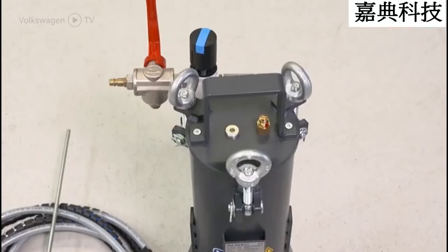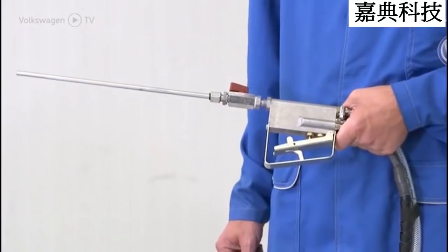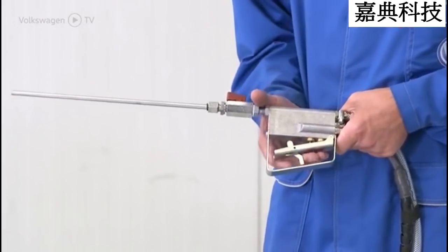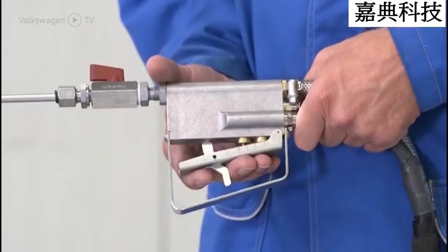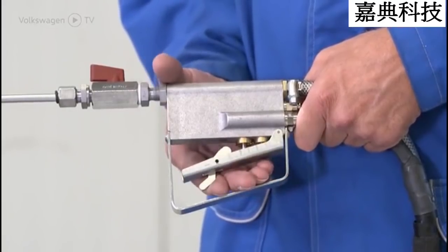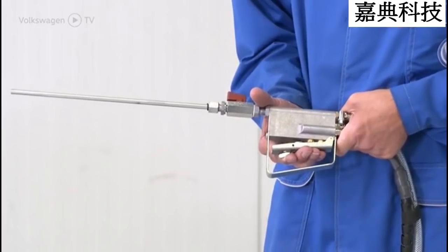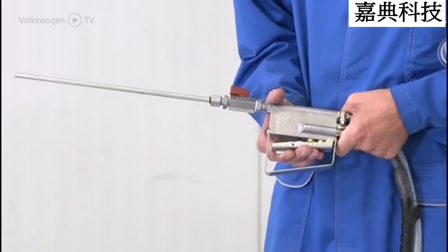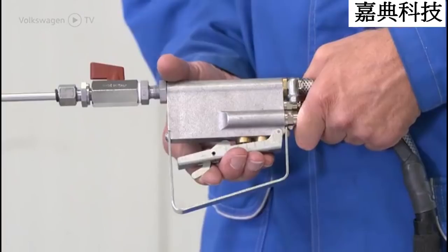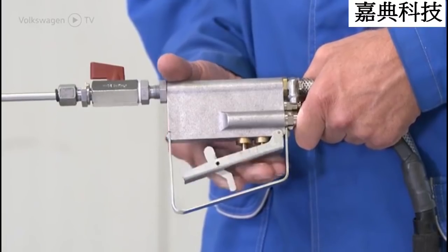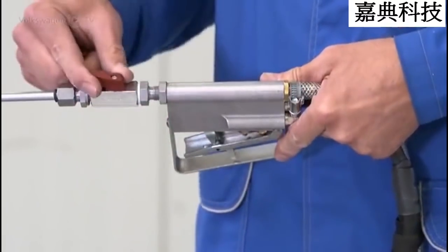Note that the lance handle has 3 functional positions. Lance closed. A catch prevents the lance from being operated accidentally. Lance level 1. The catch is loosened, the lever is pressed halfway. Only compressed air escapes. Lance level 2. The lever is pulled to the stop. Compressed air and the granulate are discharged. Here you can see a shut-off valve you can use to block the lance.